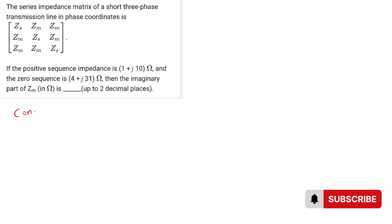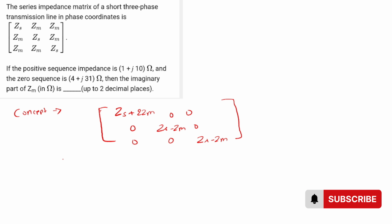The concept is that for the impedance matrix with Zs plus 2Zm on the diagonal for the first entry, and Zs minus Zm for the other two, we can write Z0 equal to Zs plus 2Zm, Z1 equal to Zs minus Zm, and similarly Z2 equal to Zs minus Zm. These are the concepts based on the impedance matrix.